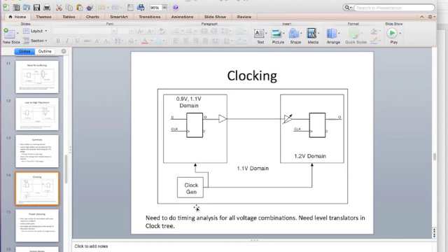Now you might run them off the same clock frequency, but the phases could have a different relationship. But again, you can use techniques. They are pretty well known techniques of how to cross and hand over signals across different clock domains. Now, if you can do that, that will be the most modular and robust way of doing your design. And that's what I would suggest. I would try to do it that way, so that I don't have to deal with a clock tree synthesized across multiple voltage domains, which makes life much more difficult, and the system is not secure.